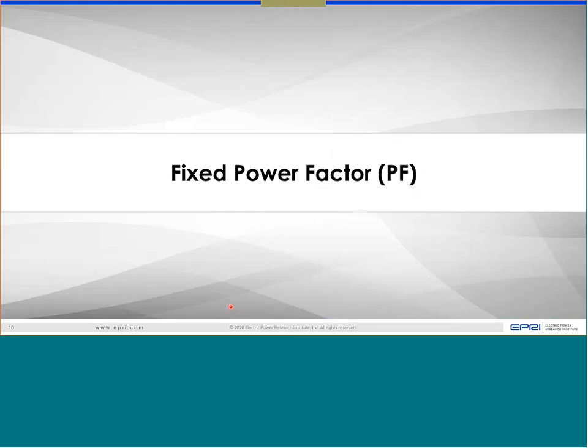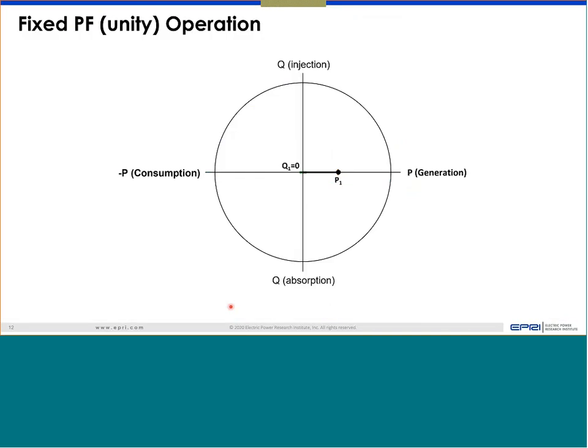So we'll start with the power factor, the simplest one and being used for several years now. It is a very simple starting point, and just to remind you, unless the utility asks for any specific function to be active, the default will always be unity power factor operation, the way it has been done for the last 10, 15, 20 years. So again, if you don't ask for any specific advanced functions or non-unity power factor setting, the default will be the unity power factor, the way I'm showing in this picture.